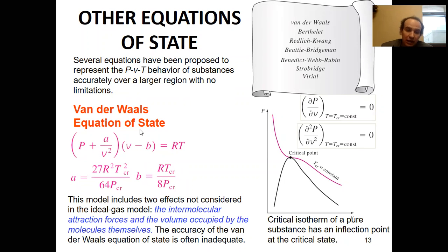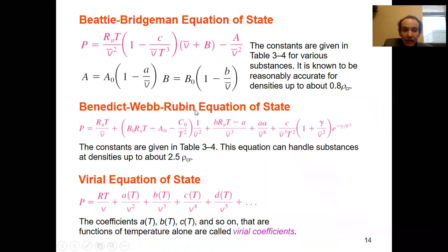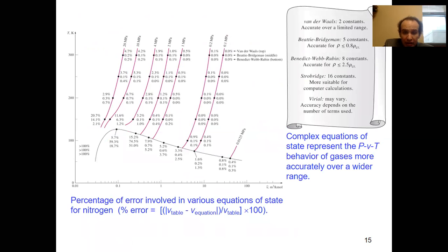For instance, when I work on combustion or on supercritical CO2 turbines, we have the so-called Peng-Robinson equation. There are many extensions of it, but that is the simplest. Here I can show you two more equations, like the Beattie-Bridgeman equation, here with different constants, and also the so-called Rubin equation with much more constants. Finally, we have the virial equation. I don't request you to remember all these equations, but you may realize that each new equation gives you more constants to introduce.